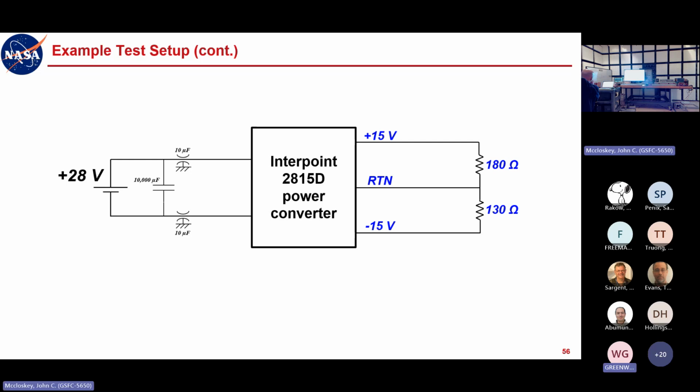I don't see stray capacitor between these lines and the chassis of that converter. Then what's giving you the path for any of that common mode to get back to the source? It's the return, but if it's the returning impedance on the return, there's no common mode. We're going to have to take this up privately, Wayne. But what I'm saying is it's the impedance that's causing the problem, because it's coming out in one impedance and they're returning on a single wire.